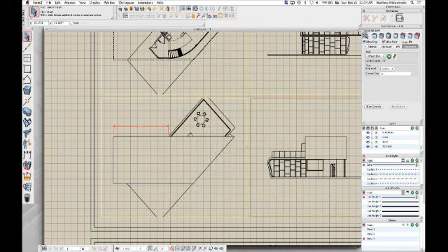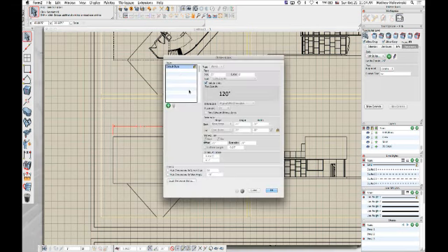Is there a way to save a new style? Yes, because anytime that you create a brand new style here, that's stored with the project, but you can actually load those dimension styles from some of the projects. So you can have one project that has all of your standard styles, and you can load those in here using this load option there.